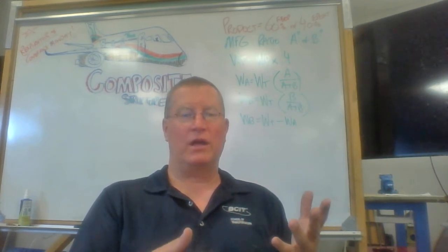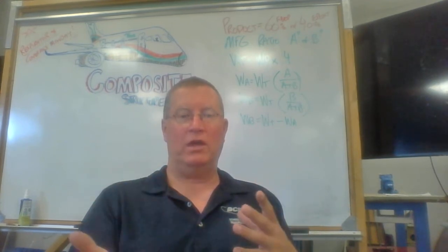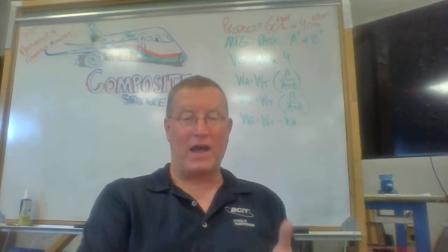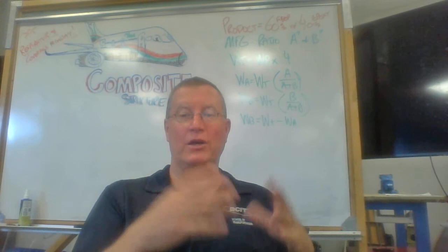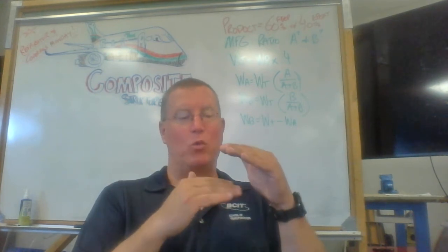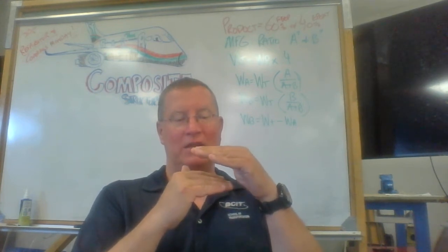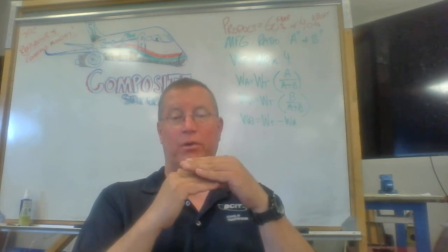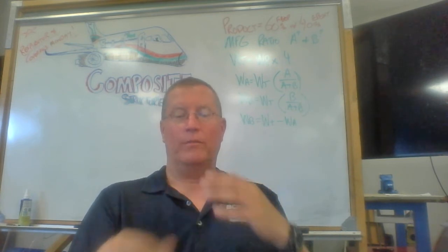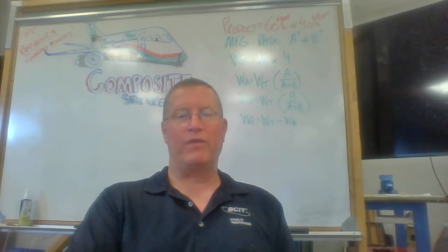Could be put inside an autoclave, which provides both heat and vacuum, and most importantly, an increase in pressure, right? If we can get more pressure between those layers and get a tighter finished product, we're going to get a stronger finished product, right? And so that's the main value of having the autoclave.